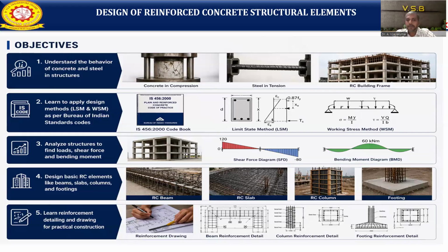We should know about the various shear forces as well as the shear force diagram and bending moment diagram. Where is the maximum bending moment, where is the minimum bending moment, where is the negative bending moment. Everything we should know before starting the process of the reinforcement detail. So based on the shear forces and bending moment only, we can provide where the minimum reinforcement and maximum reinforcement, where the positive reinforcement and where the negative reinforcement. We should know about the shear force and bending moment conditions.